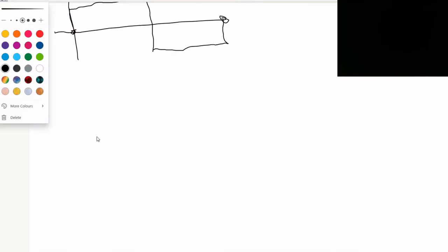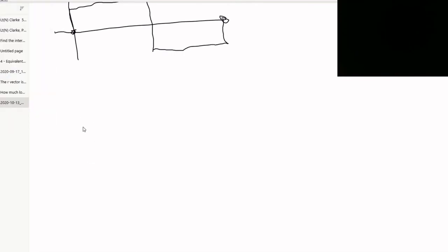As for how a point moment is going to affect things, if we start off with just this beam that's simply supported here, and we apply a positive moment in the center here, it's going to cause that center to want to twist like this.